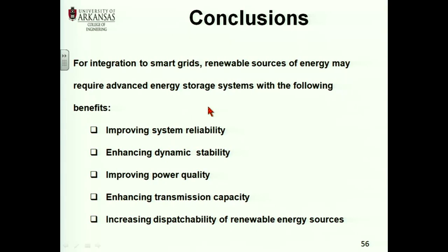So that means that whenever there is a big increase in the demand for power, you need power immediately. Energy storage can do that. Why? Because you have power electronics. Instantaneously you can tell those IGBTs to start switching and start providing power. A natural gas generator is going to take 2, 4, 5 seconds or more, so you're going to have a drop, right? So that's the reason why it's attractive.